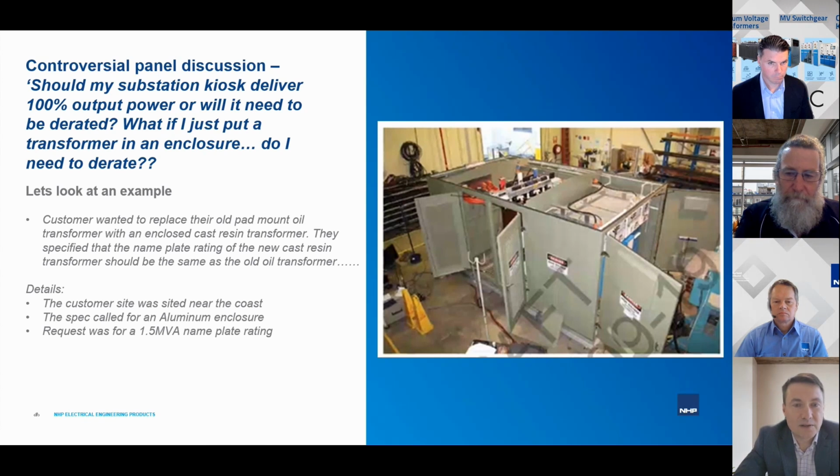It's quite interesting what Mike just recently said, that in his modeling with his design of enclosure around the old transformer, the impact of forced ventilation was actually minimal, which makes sense, because that design was fully optimized for the airflow, which probably wasn't the case for this particular substation, and the way that the switchgear and the transformer were installed, switchgear being quite large, and the cast resin transformer installed in such a way that you cannot really achieve very high air velocity.